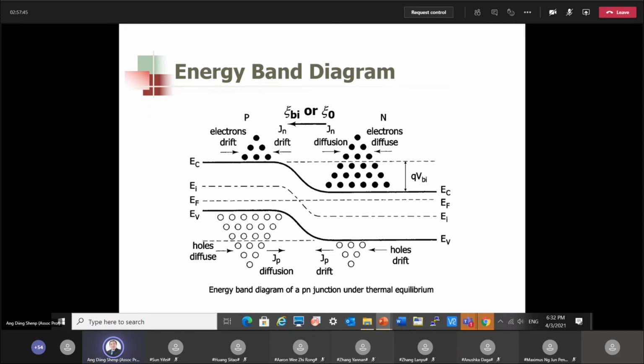By the way, a PN junction formed using different semiconductors is called a heterojunction, right? So you can still understand the behavior of a hetero PN junction in the same way as a homo PN junction, except that there are certain things that we need to consider now because of the two different materials. One of which is the discontinuity of the electric field at the metallurgical junction. But this doesn't affect very significantly how the PN junction performs.